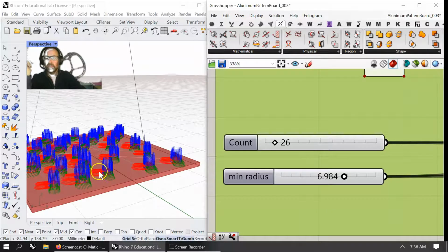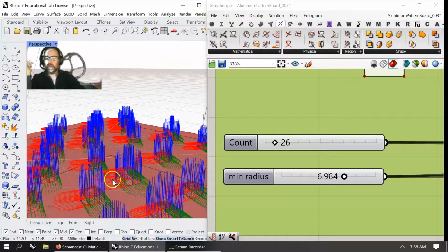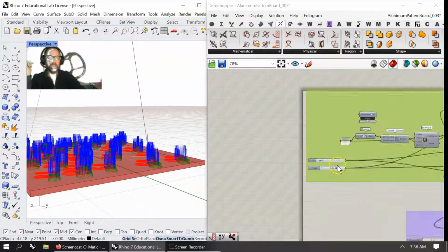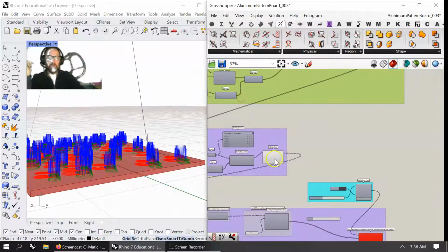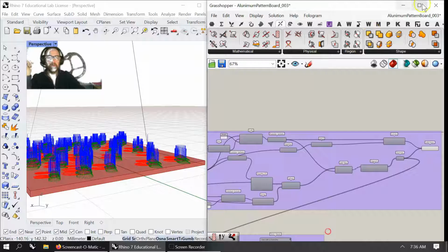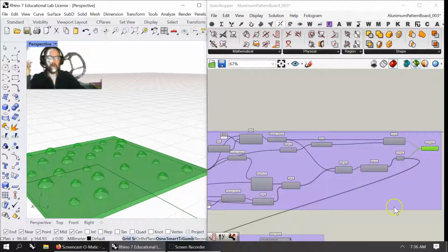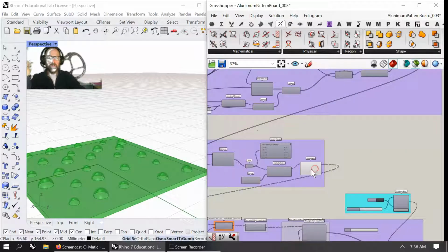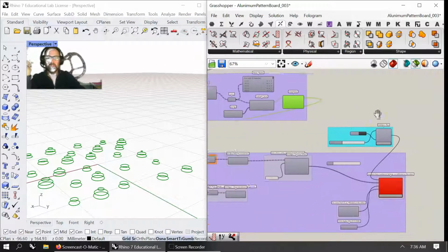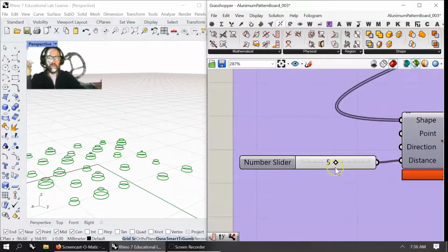So you get these little circular patterns and tool paths are dropping in the spindle to mark these edges. You can see that now we have a lot less. If we take this off, you see we have less little bumps that are going to be on our pattern mold, and then of course less contours, which then have to be traced. And you can change the width of that. If I brought this down to say 2, you're going to see there's going to be many more tool paths.